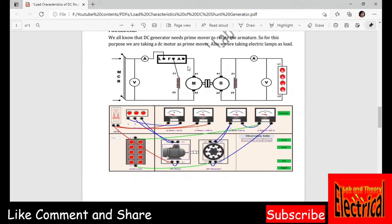So this is the starter. Okay, this is the starter, you can see here. I have taken the same symbols, try to take the same symbols so that you will not get confused. So this is the L. We have connected one ammeter terminal to L and one ammeter terminal to the MCB, and then it is connected to the motor, right?